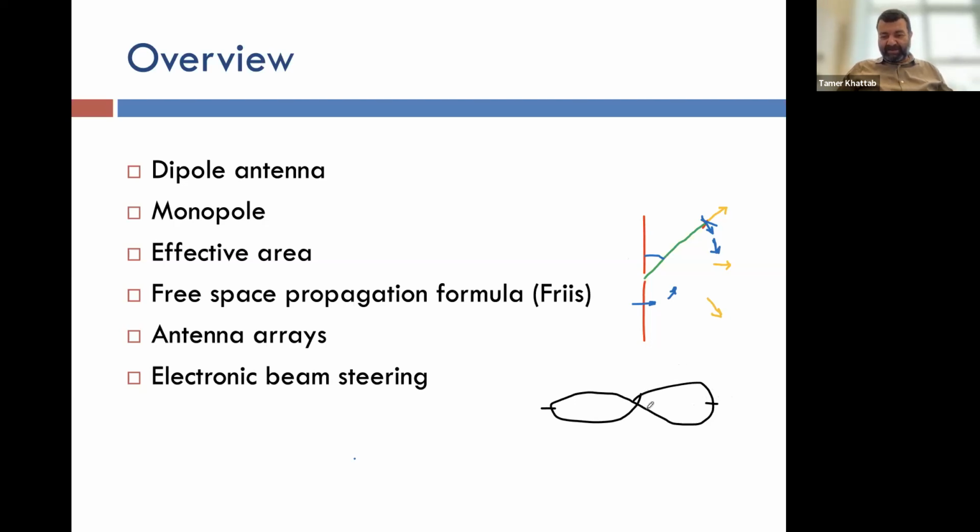What does this radiation pattern, in general, as a characteristic of an antenna, define for us? It shows us how the antenna is concentrating the radiated power in certain directions. Now that's just showing it. If you want a quantitative measure that tells you how that compares to an antenna which is not doing the concentration, we call that the omnidirectional antenna. We found that there is a property called directivity, and that directivity defines, in the direction of maximum radiation, how much is the energy or power concentration compared to an antenna which is not directional at all, which does not concentrate the energy in any direction.